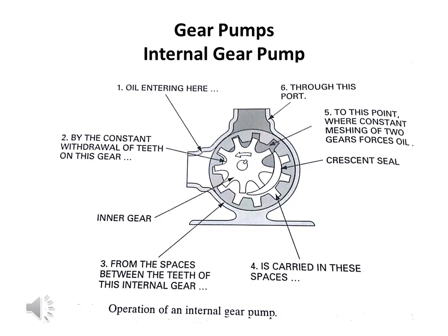Now the inner gear is attached with the motor, and whenever we switch on the pump and the motor starts to rotate, the inner gear also starts to rotate, and along with the inner gear, the outer gear also starts to move. The left side port is the inlet and the top one is the outlet port. Now the inner gear will be moving away from the outer gear. When it is moving, suction is created, and through the inlet port the oil gets into the pump.